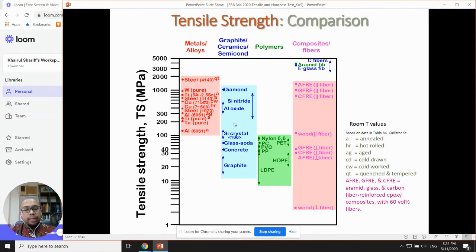But now, most of the material engineers try to replace the pure metal with something like the composite materials. In composite you have a different type of composite, right? You have CMC, you have PMC, you have MMC. What is a PMC? Is polymer matrix composite. CMC is ceramic matrix composite, and MMC is metal matrix composite. Nowadays, people are moving faster in PMC, polymer matrix composite, meaning that they try to formulate the best formulation in order to produce the polymer composite that can have relatively similar tensile strength, even higher.